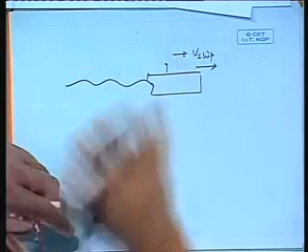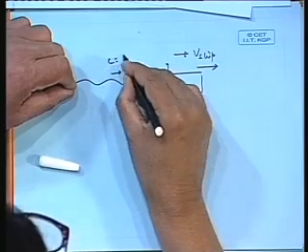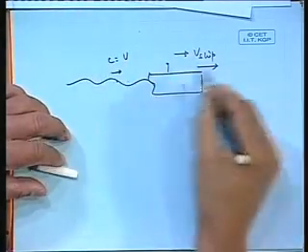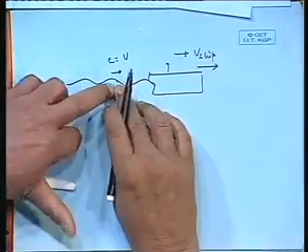These 10 waves would have 10 different speeds, because I mentioned that before. The one that is not moving at your speed, very soon you would not see it. You have gone ahead and the wave is much behind, or it has overtaken you. So the only wave that stays with you is the wave which has c equal to V. So when the ship moves, it only makes one particular length of waves, because all other waves would have dispersed away. You won't get to see them. This wave is so steady that you think it is stuck to you. If you take a picture here today and tomorrow after breakfast and the next day, the crest is still at this location. So you think it's a stuck picture.